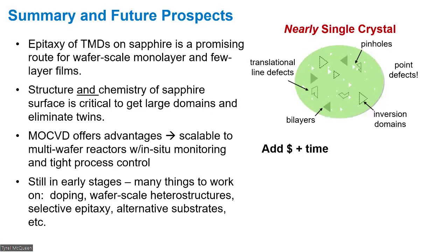Once you have all the positioning figured out, how would you pattern it? Is it a regular photoresist? Yeah, that's a good question. I think what's currently being used is still traditional. E-beam lithography is used, and you have your e-beam resists. I don't know that anyone is working on alternatives right now, but maybe that will be necessary.